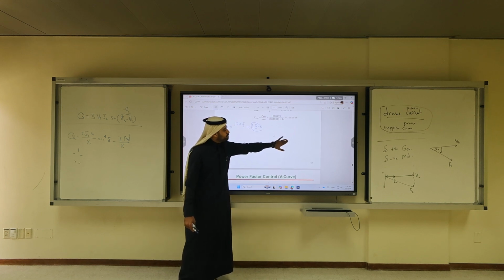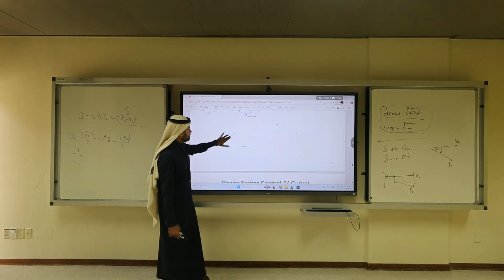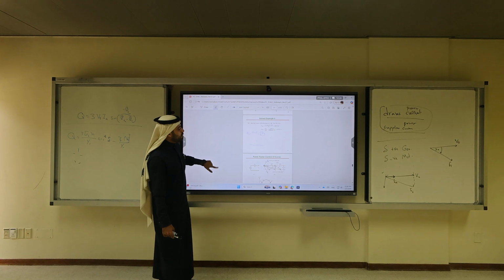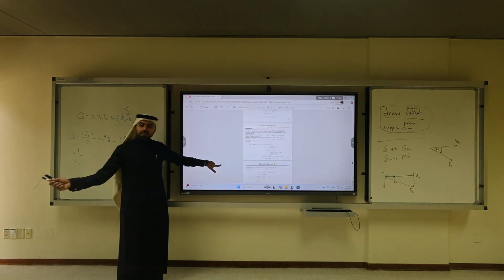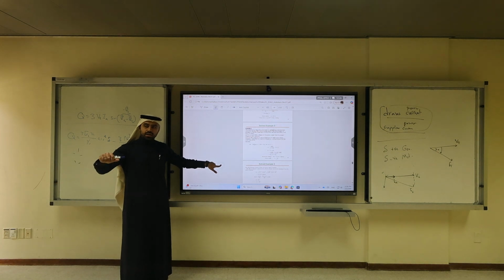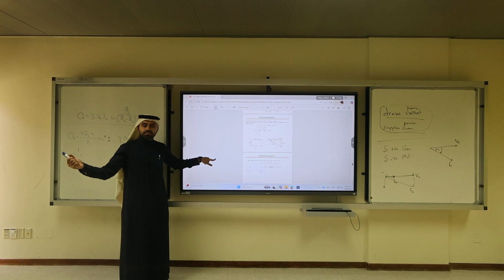It's a combination. This is physics. Okay, let's continue. So, any question about example number 5? So, unity power factor, I angle is 0. Maximum torque, delta is 90. And can we operate our motor at delta 90? No, that's the maximum torque. You should not even be close.